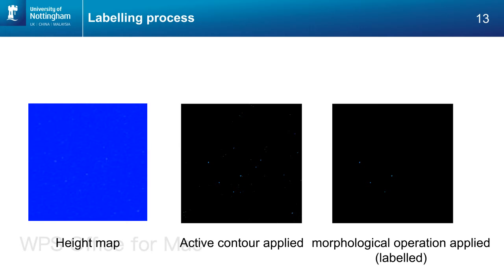Height map was constructed to represent the real surface topography, since the result needed to be labeled pixel-wise to achieve accurate segmentation. Then the height map was labeled with the use of image segmenter, which is a built-in tool in MATLAB. Then the image was split into subsections and those images were transformed, for example, flipped, rotated, etc., to augment the database for a more accurate training.